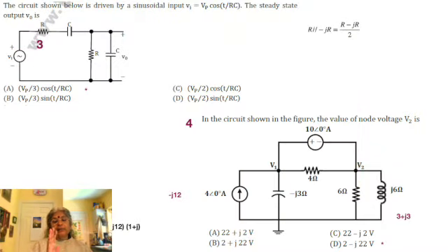We see that the 10 ampere current source and 5 ampere current source together deliver 15 amps to the 100 volt source, making it a consumer, since the voltage and current are in opposite directions, of 1500 watts. The 10 ampere source, on the other hand, delivers, because 100 volts is across it, 1000 watts.